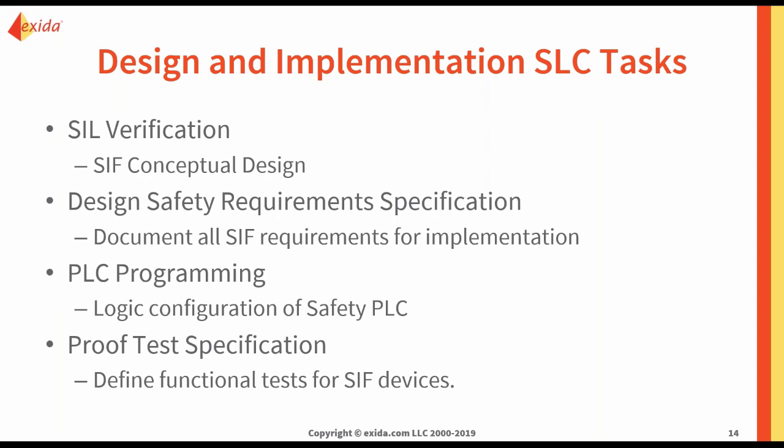And then once it's time to implement, you need the proof tests. So you want to define those functional tests for your SIF devices that you can use throughout the life of the plant to ensure that those devices are working and can respond effectively to a hazard and bring your process to the safe state.